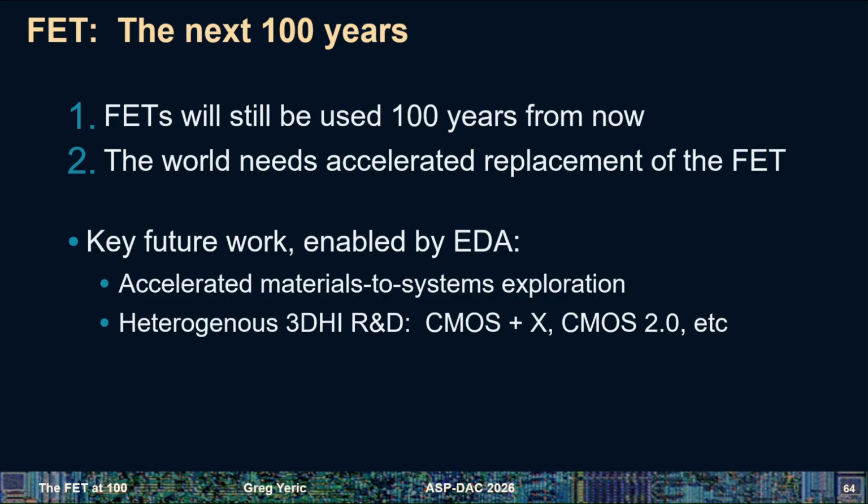And then 3D-HI, so 3D heterogeneous integration. CMOS plus X is a buzzword where it's basically, we know everything at the end of the day still needs CMOS. That's the fundamental, known, reliable way to do computing. But then on top of the CMOS, physically on top in the case of 3D-HI, you could have an analog neuromorphic circuit. We'll talk about that. So you can do computing.